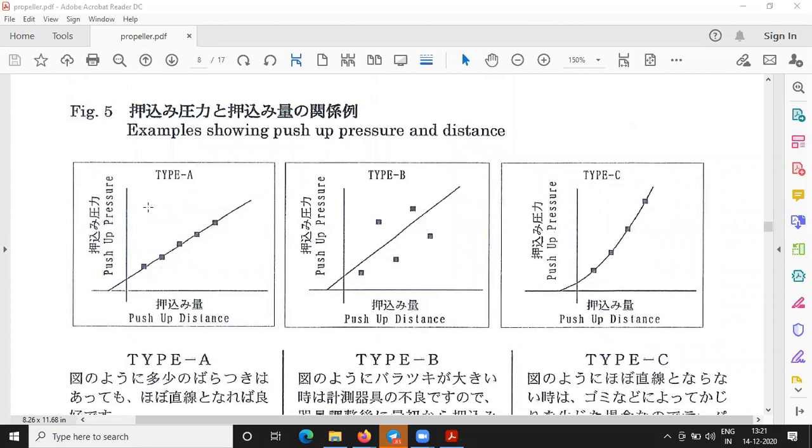First thing you saw the human error. Second thing you saw the apparatus error. Now the third thing, you should get a linear line, but sir, you are getting a line which is exponential. Yes, sir. This apparatus, the pressure got from the hand pump, that is faulty, sir. Yes, sir, that is faulty. Okay.